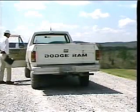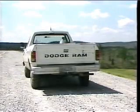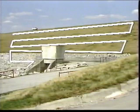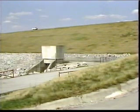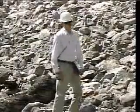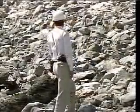There are two commonly used ways to cover slope surfaces: a series of parallel passes and using a zigzag pattern. Parallel sweeps are recommended for a large embankment dam or one that has a steep slope. The zigzag path is generally preferable when the embankment slope is small or not too steep. At regular intervals during your inspection of the slope, you should stop and look around in a 360-degree circle to be sure you haven't overlooked some important feature.